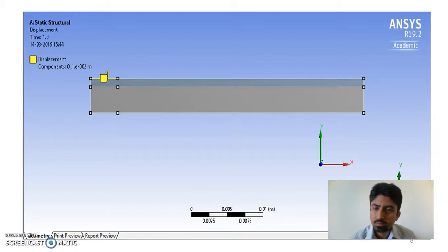In my further work, I'll define the crack tip, the crack region and the coordinates of the crack, then the crack location, that is only the coordinates. I'll find the energy release rate, that is the energy that will be driving the crack. All this work will be done in ANSYS Structural Workbench. Okay, so this was my second progress report. Thank you.